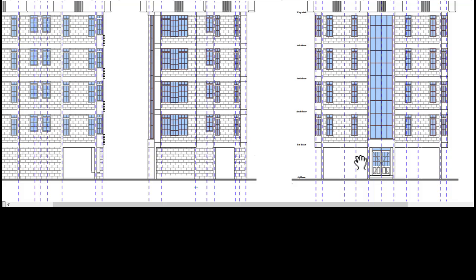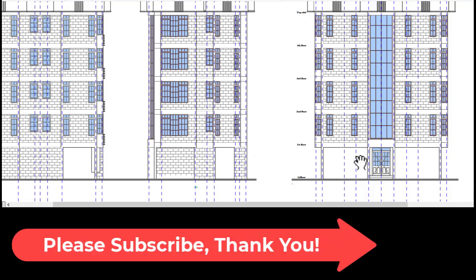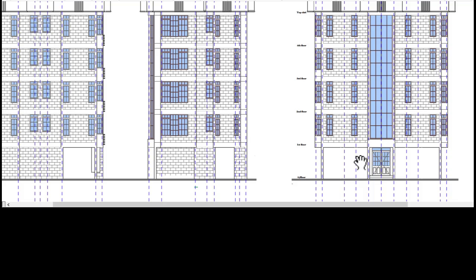What you can do, of course, you can get the width right from the plan, okay, it's indicated. But then now on height, you can always use what you call the standard height. So the standard height would mean, normally, of course, for internal walls, you just have the internal doors to worry about. In most cases, the doors that you have, they always go up to the soffit of the beams.